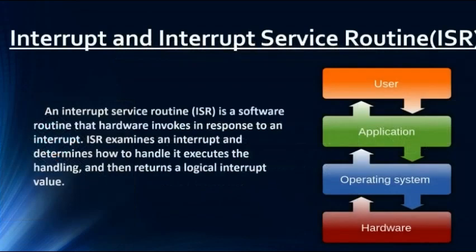Another concept covered was interrupts, where we got to know what an interrupt is and how we can handle the interrupt through the interrupt service routine, and some of the procedures to place the address in the program counter. And also we learned a term called GIE, the global interrupt enable bit, which maintains the enabling and disabling of the interrupt.